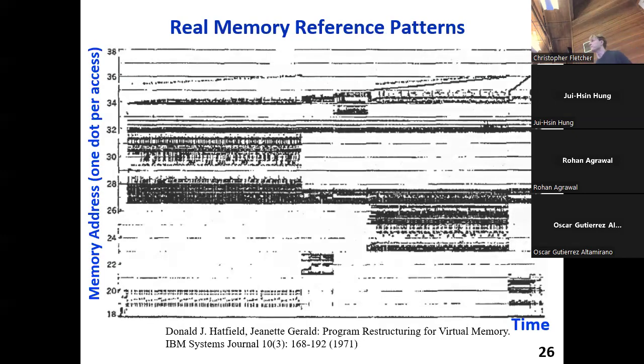Okay, so we've built up this memory hierarchy at a high level. What do memory access patterns actually look like in programs today? This sheet shows over time on the horizontal axis and the memory address on the vertical axis what a program's memory address pattern might actually look like.